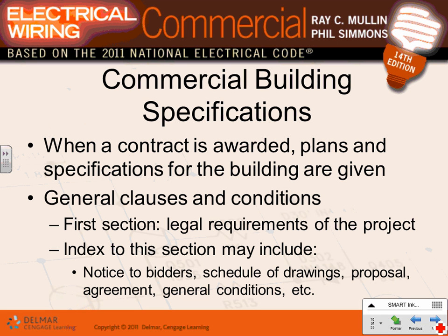The only thing I want to emphasize, if you want to be designers, is two things. As a designer, you're not allowed to work on energized equipment or non-energized electrical work. You're not licensed, bonded, or insured, right? But you will be in situations where the electrician is working on equipment and you are around them, or you have to stick your head in to take some pictures to modify switchgear. Be aware of the hazard.